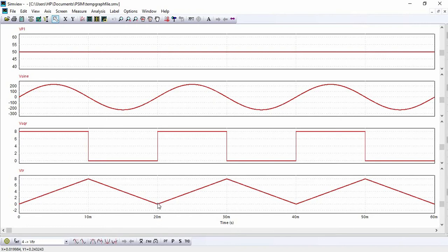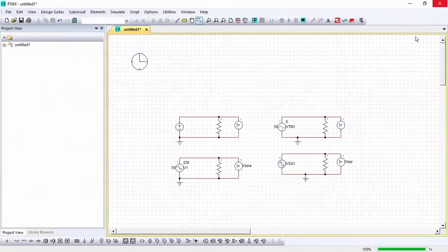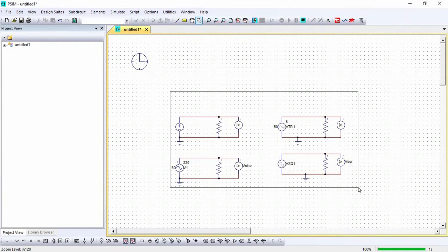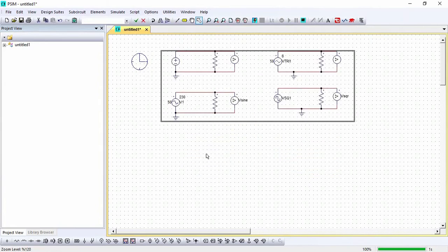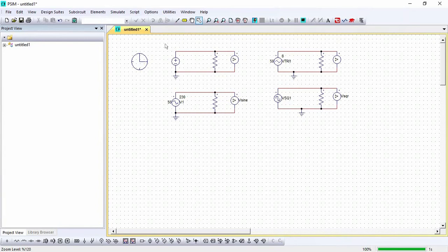It's 20 millisecond. So it is all about our different type of wave generator. It can be used in the gate signal of semi-controlled and fully controlled switches like thyristor, MOSFET and IGBTs. Here today we're not going to dip into that, but we'll try to see the uncontrolled rectifier, meaning full wave uncontrolled rectifier. Here for the uncontrolled rectifier our switch will be diode.